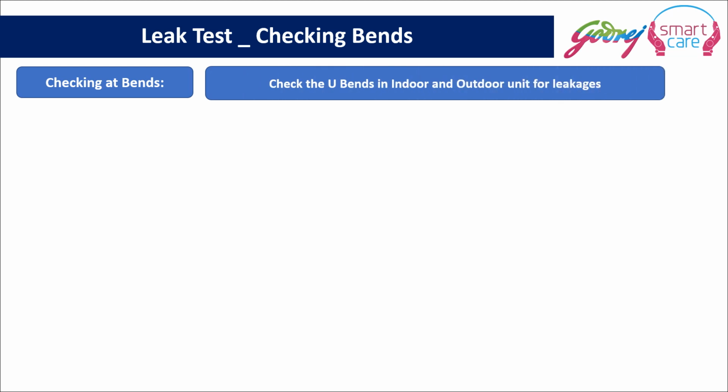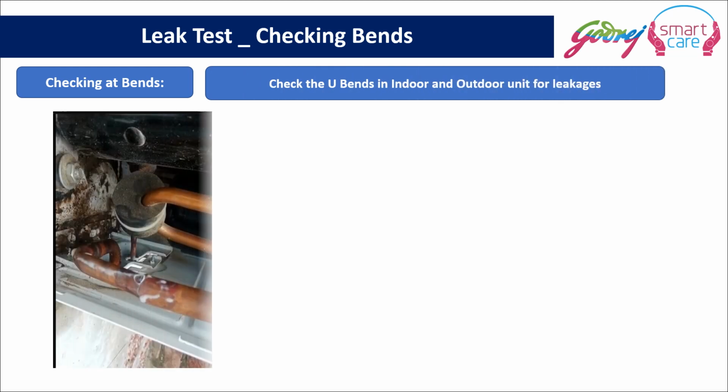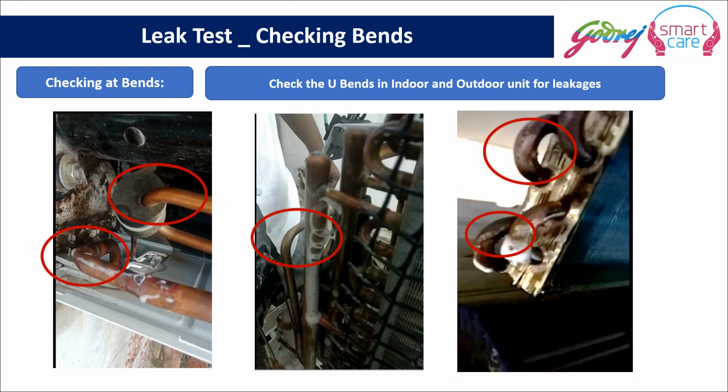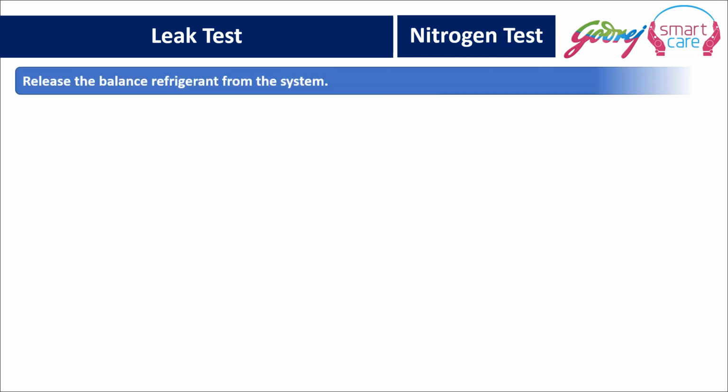Then we have to check the U bends in the indoor and outdoor unit for leakage. We have to carry out a leakage test.